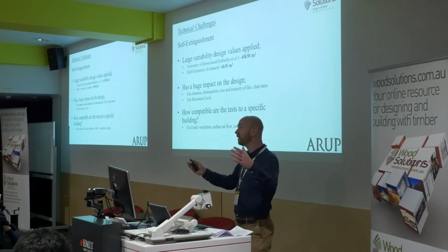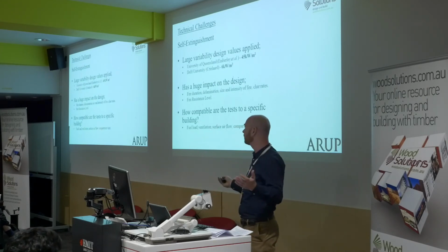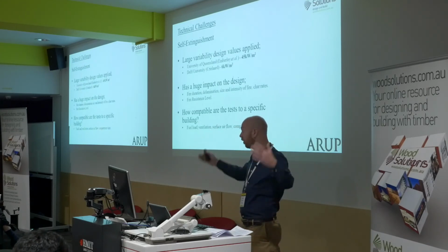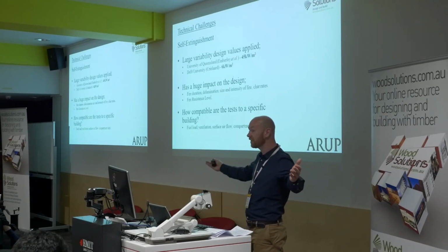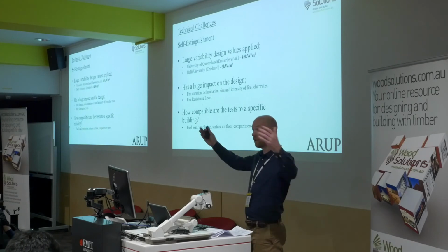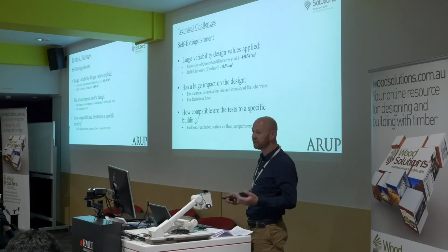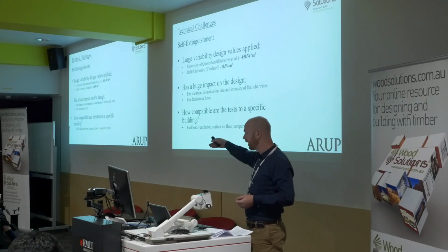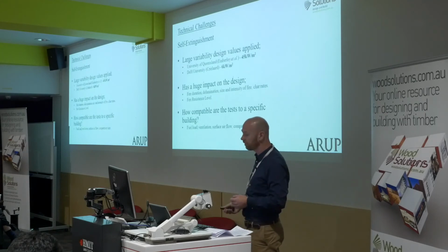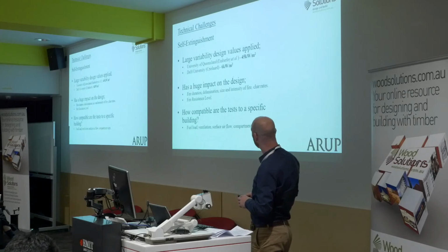If you have a fire here and anywhere outside of 45 kilowatts per meter squared ceases burning, then you'll get a fairly small area of impact. Whereas if you extend that to 6 kilowatts per meter squared, you get a much larger burn area, much larger burn duration, and it has a serious effect on the fire dynamics within the compartment. It can re-radiate down to furniture over there and cause a travelling fire. Then you can get a big fire.